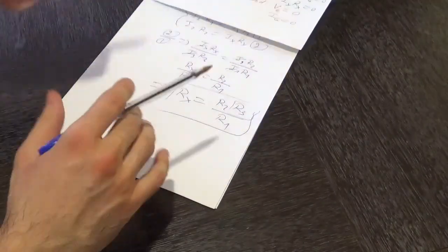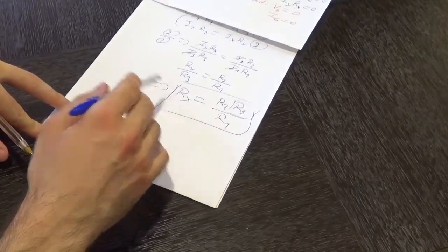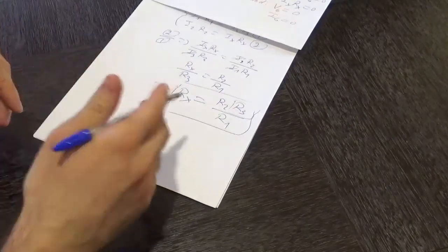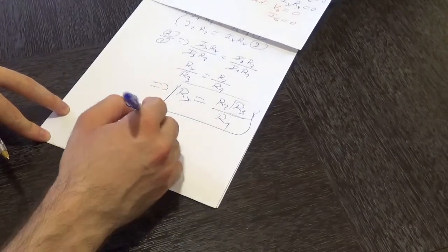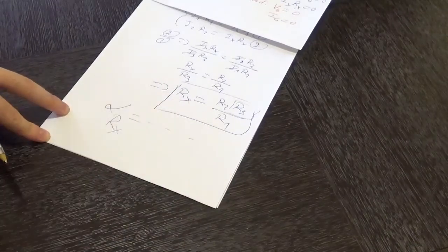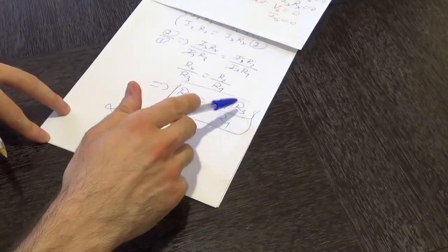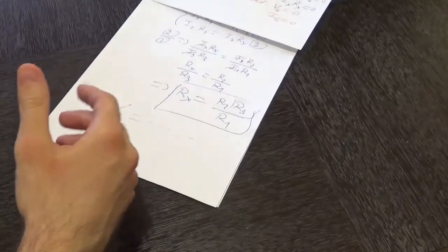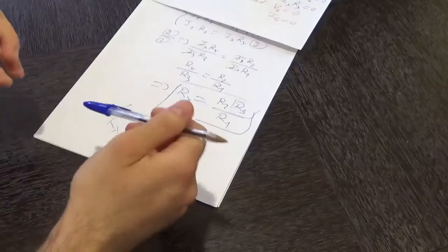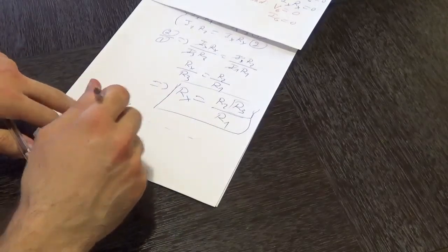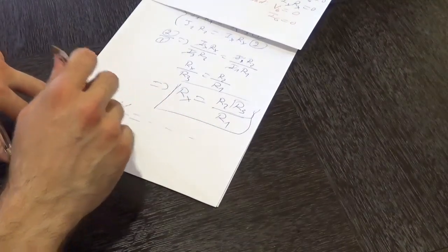Now in our experiment, we are going to apply that equation in order to determine a value for that unknown resistance. Moreover, they are also going to ask you later on to determine a certain error on Rx, which is none other than propagation of error. Since Rx is dependent on R3, which is a variable resistance, meaning a resistance which we are varying ourselves, it's going to have a certain margin of error on it. Therefore Rx is a function of one variable,